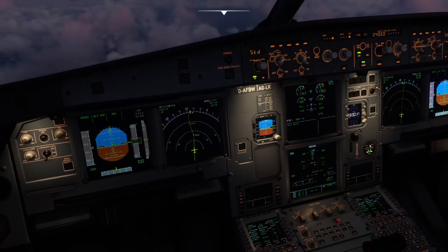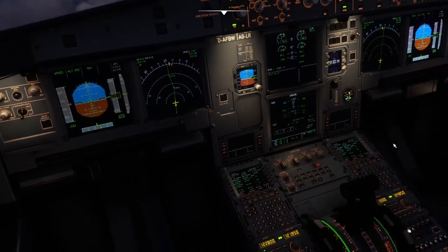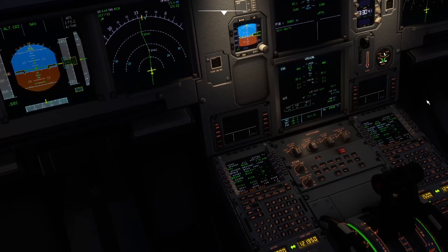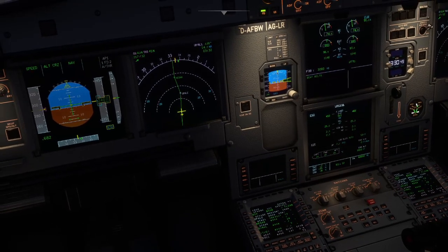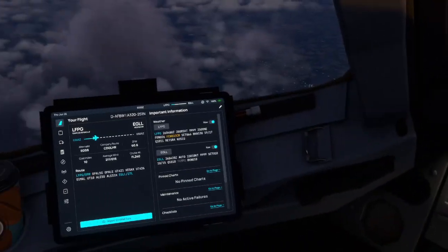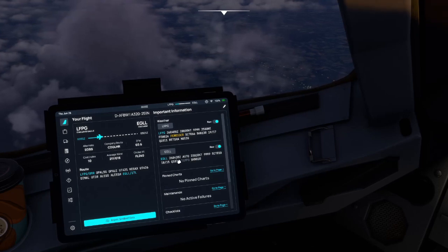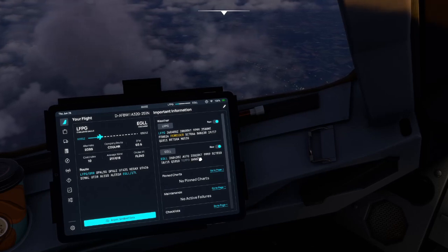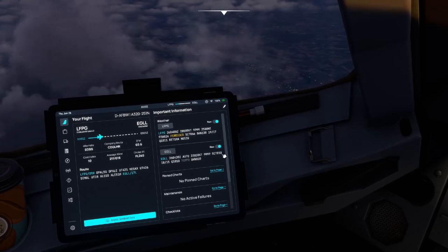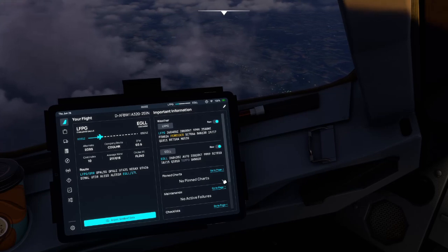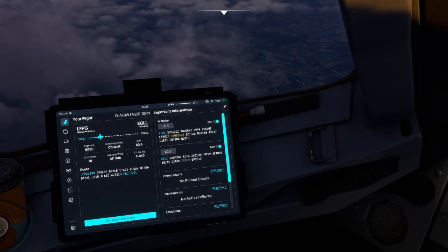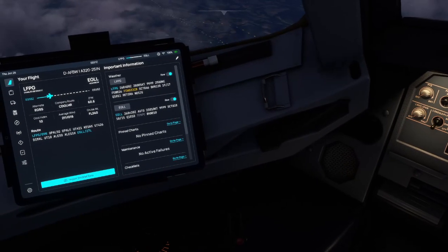There we are, welcome back. Jet establishing the cruise, 148 miles to go to Heathrow, expecting to land with 2.6 tonnes of fuel, so stacks, and probably time to think about getting myself organised. In London today, the weather, light westerly breeze, 10 knots, all the nines at the moment, clouds scattered 1,000 feet, 18 degrees on the ground, 1010, so let's have a think about getting ourselves there.